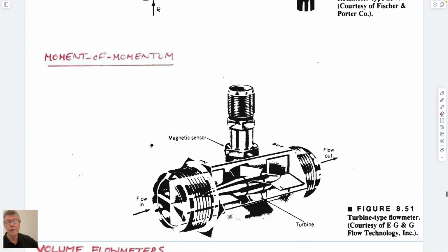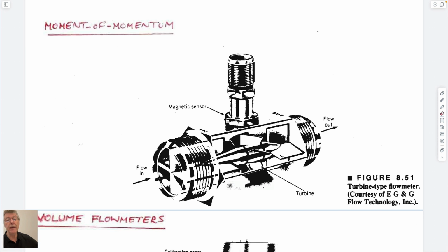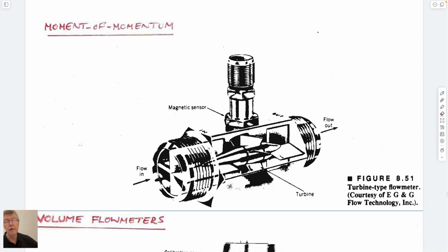which you could calibrate, of course. You could imagine impellers in tubes, where you can measure the rotation of this, I presume by a magnetic sensor. You could put a coil around it, just like a small electric motor or a generator. You could measure the voltage that you produce from this, or you could measure the number of clicks that you get by it turning in the flow. Clearly not a solid state measurement, because you have moving parts.